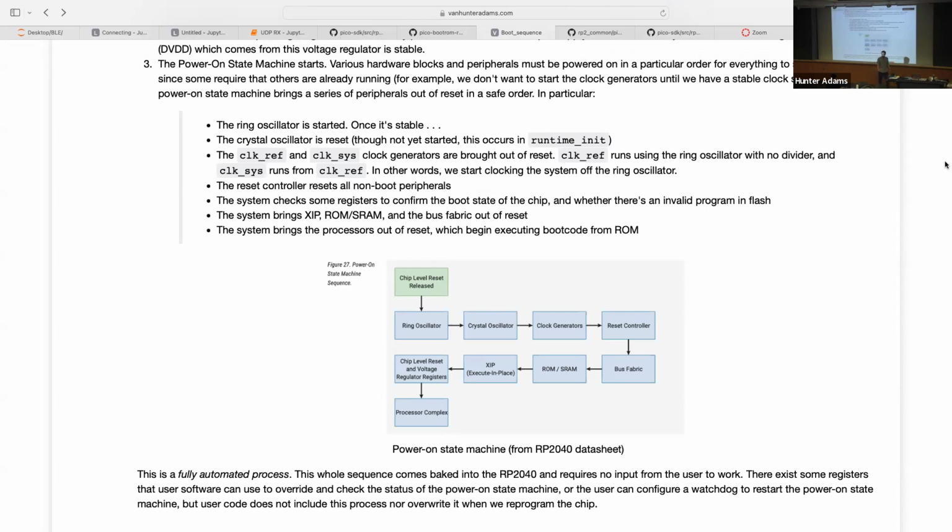For some applications, that's great to know about because it means that you can run your system off of a lower power clock at the cost of stability of the frequency of that clock, but there are a lot of applications for which that doesn't matter. There are a lot of applications for which that does matter a lot. This in particular would make it really hard to interface with external stuff that requires a stable clock input.